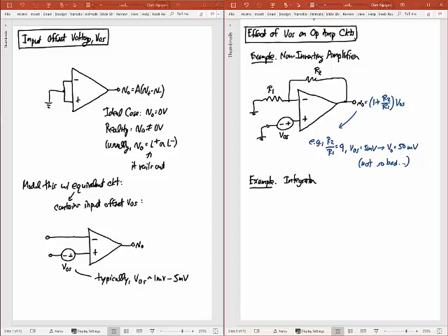Okay, so you've been analyzing some op-amp circuits now, and one of the op-amp circuits you analyze, or at least something that comes close to something you analyze, is this one, where I'll put my plus here, I'll put my minus there, and now I'm going to have still a resistor going to the negative terminal, but now instead of a resistor in feedback, I'm going to put a capacitor in feedback. And that then is what goes to my output there. Okay, let me leave myself some room here and give myself a little bit more room.